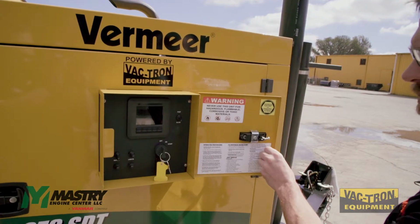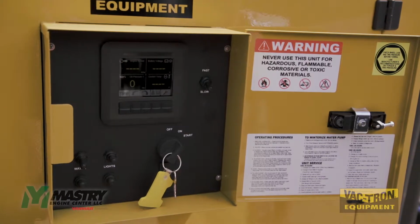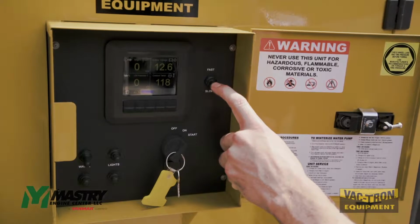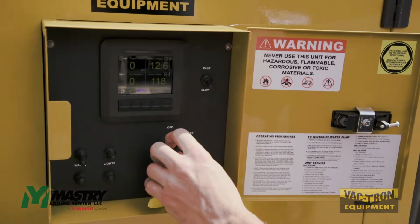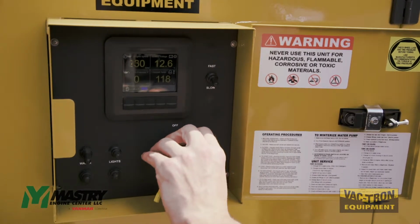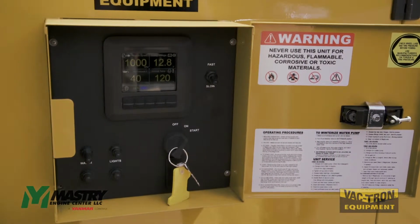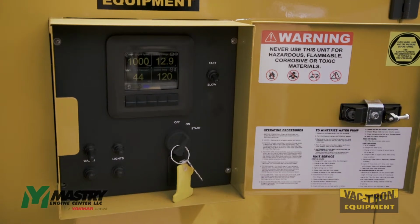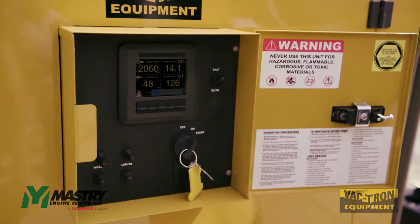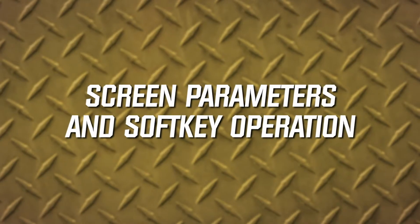To start the engine, you'll turn the key to the on position and wait for the panel to boot up. Then once you get past the splash screen, you can crank the engine by turning to the start position. And then the engine is running. Then to increase the speed to the fast setting, just flip the toggle switch up, and then the engine will go to 2500 RPM.